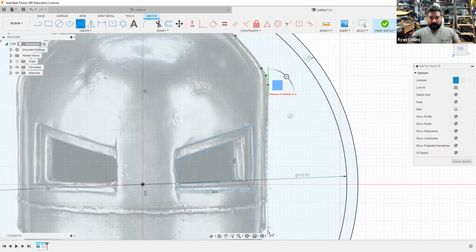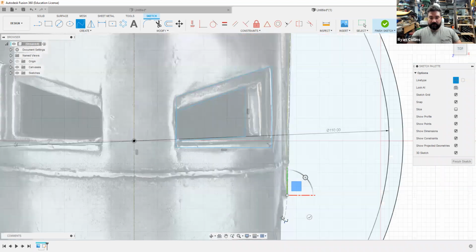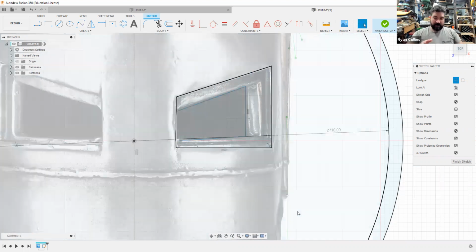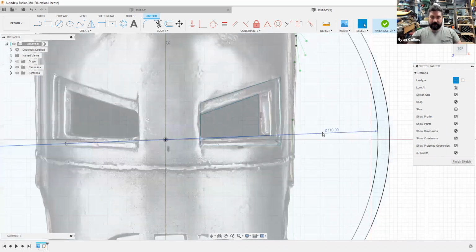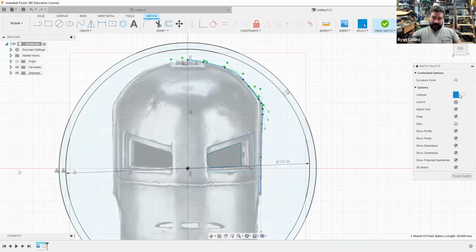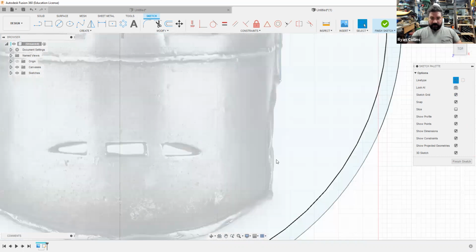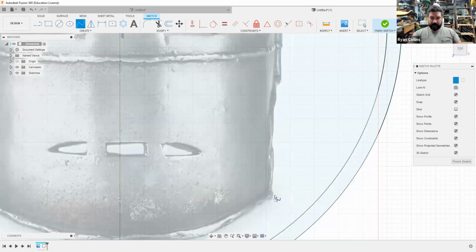I drag this way down, that's all going to be pretty well a straight line. Problem is then when I make another selection, it's going to start to flex. So this might be a good point. Hit enter, let that line be finished. And it looks like I forgot to change back over from construction line. So if I select this line, you'll see over in my sketch palette, line type, deselect construction line. Now it's back to being a regular line. We're good. So I can keep working, start a new fit point spline right there, and just kind of work my way up. Close enough, close enough.